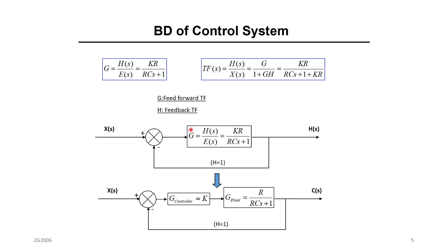This is the feed forward. Here you see the transfer function of the controller and the transfer function of the system, of the tank before adding the controller. And this is the feedback, the sensor, which is usually equal to 1 because you want to measure exactly how much the output is and compare it to the input. So this signal will be the error.